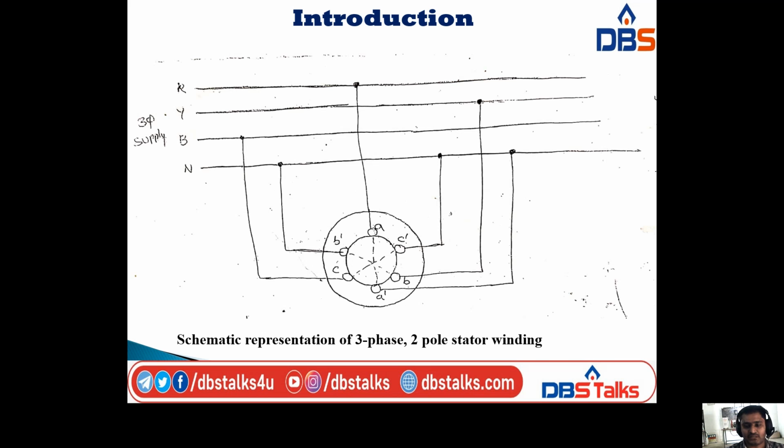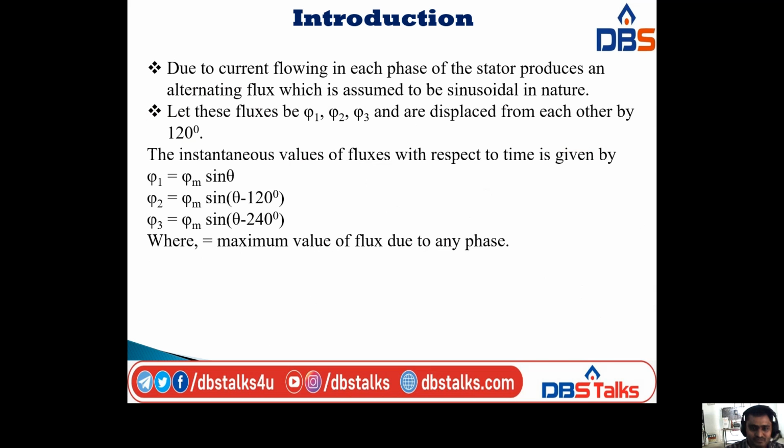Coming to the procedure, how we produce the rotating magnetic field in the synchronous motor. Due to current flowing in each phase of the stator, whenever we give the three-phase AC supply to the stator, we have current flowing in those phases. Due to current flowing in each phase of the stator, it produces an alternating flux, which is assumed to be sinusoidal in nature.